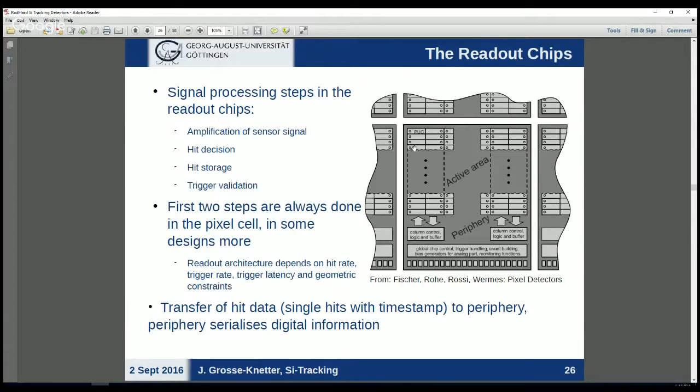And in that cell, you have to take care of an amplification circuit. So that reads in the induced current signal, does some sort of integration, and then hit detection and a storage mechanism. That all belongs in the pixel cell. And at the bottom, with some sort of digitization, you digest those data. Typically in high energy physics, we have a trigger because we filter certain data. We don't write out everything that is received compared to what we saw in the detection mechanism. Then data is typically serialized and written out on digital data links.